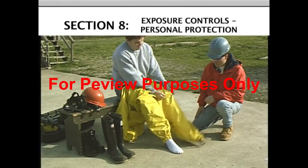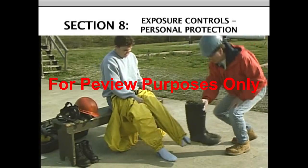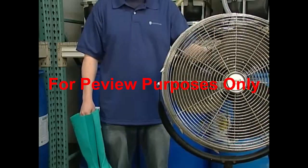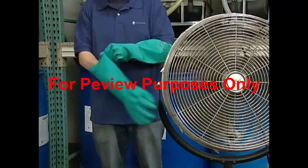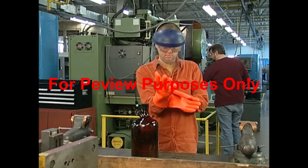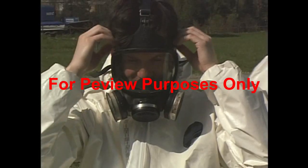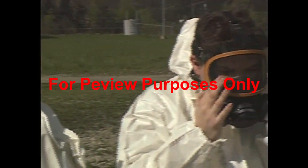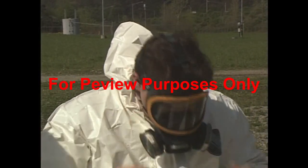Engineering controls, personal protective equipment, and exposure guidelines are addressed in Section 8 of the SDS. Engineering controls might include things such as the use of local exhaust ventilation systems when working with a material. Recommendations regarding personal protective equipment focus on minimizing the risk of exposure to the material. For example, to provide respiratory protection, an SDS may instruct you to wear a NIOSH-approved air purifying respirator equipped with organic vapor cartridges or canisters.